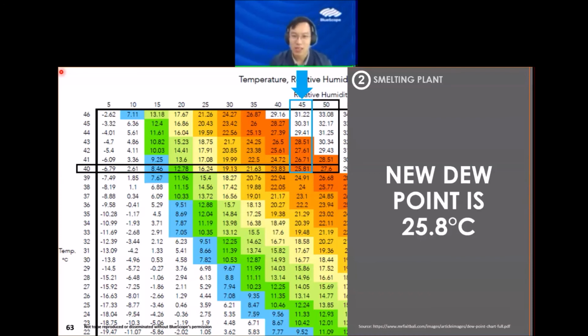How long it will last depends on so many factors I mentioned earlier, right? The temperature, curing temperature, the type of paint, the condition of the surface where you paint over it. So the no is because it depends on too many factors. Most often, owners will get one or two things wrong, and then the result will be bad, right? So my answer is yes and no.